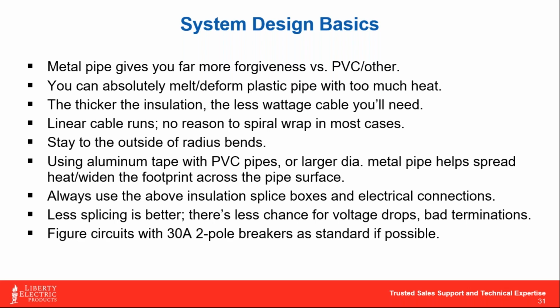That's just basic logic, right? Many times the insulation can get expensive. So sometimes we see a little bit of a balancing act between, hey, what cable versus how much insulation. But know this, once you start getting up into 1.5 inch, 2 inch insulation on that pipe, yeah, you're not losing a whole lot of heat. So it definitely helps the efficiency and being able to lower the output of the cable.